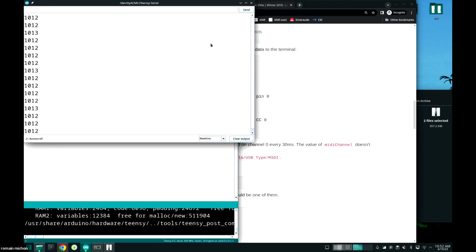on the FSR. Because the problem with analog pins on the Teensy, and that's the same for Arduinos, is that you always have electrons kind of floating in those pins. And so if you're sending a current which is very low, it's very hard to measure it because there is no ground, and so the electrons are floating. And so here with the 10K resistor, I'm sort of bringing all these floating electrons to the ground, okay? And so this is very important.